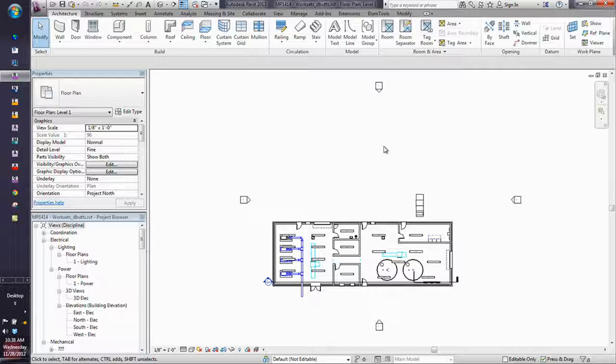The one thing you need to know about Worksets is that it's not a problem to have a whole bunch of Worksets in a project. It's a problem to have a whole bunch of open Worksets in a project. So you want to use the Worksets to control visibility and make sure that everything you want to use is turned on and everything you don't need is turned off. And by doing it by Workset instead of by object style or any other instance, it makes it a lot faster. So the models regenerate a whole lot quicker.